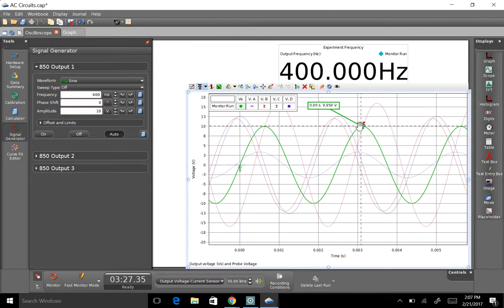trying to find the peak here, it should be a green box with an arrow that's vertical when I was moving it. So the source shows 9.959. Now, I don't think I'm good enough to get that last digit, so I just go with 9.96 plus or minus 0.01, right? Because just my little hand shaking is enough to make it significantly different as I move it around. Okay, so that's the voltage source.